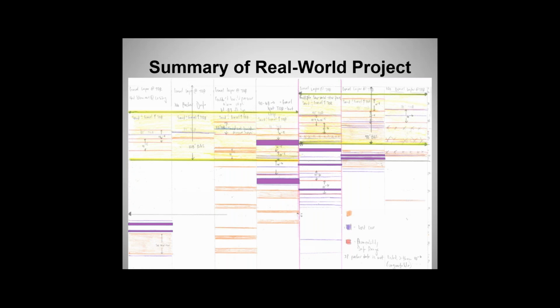Maybe we drilled these holes and had a geologist out on site, or maybe a third party drilled and logged these holes. You just have the boring information, you've got nothing else, so you're looking for everything. Did you lose the drill core because it washed out? Did it fall out of the core barrel? Could you not find it? Did it not make sense where it went? All you know is that you don't have core here.